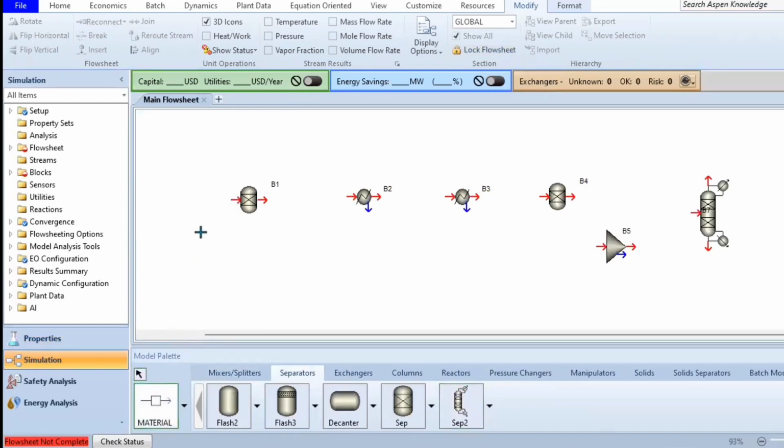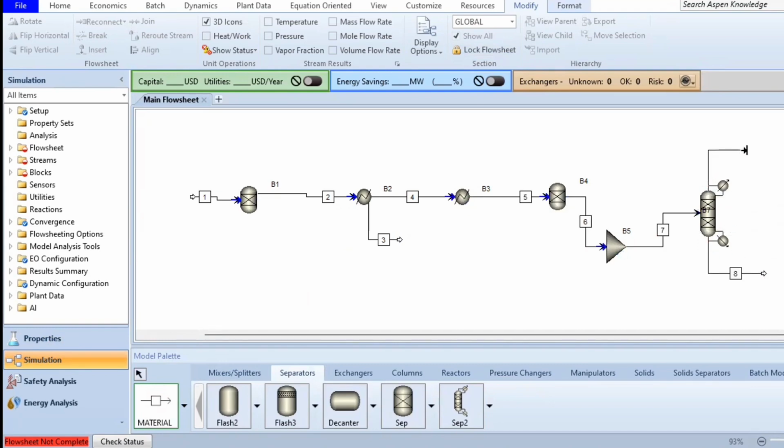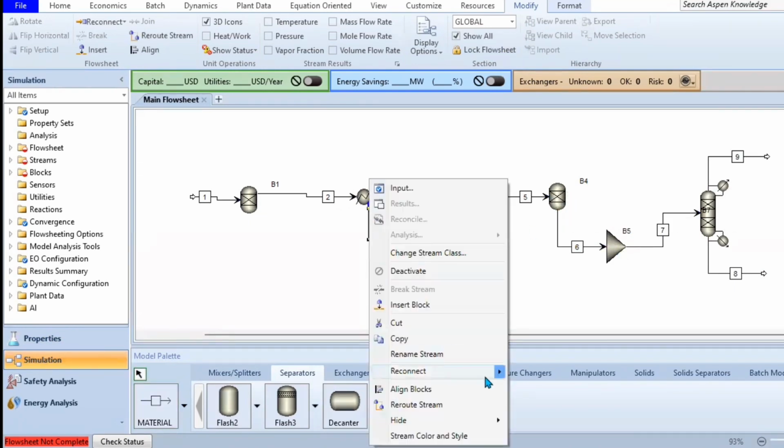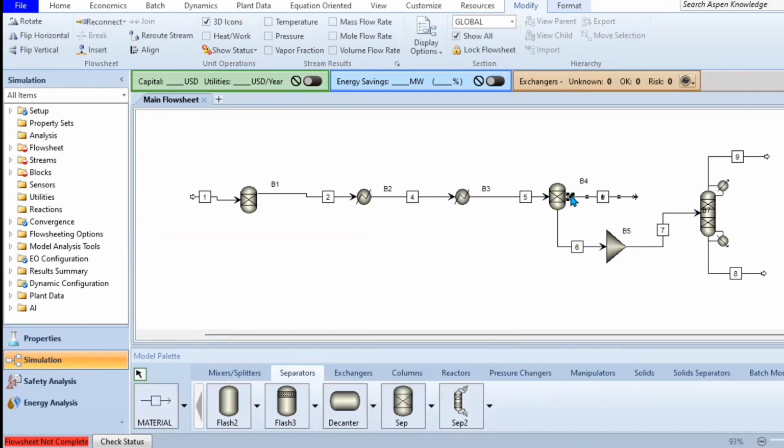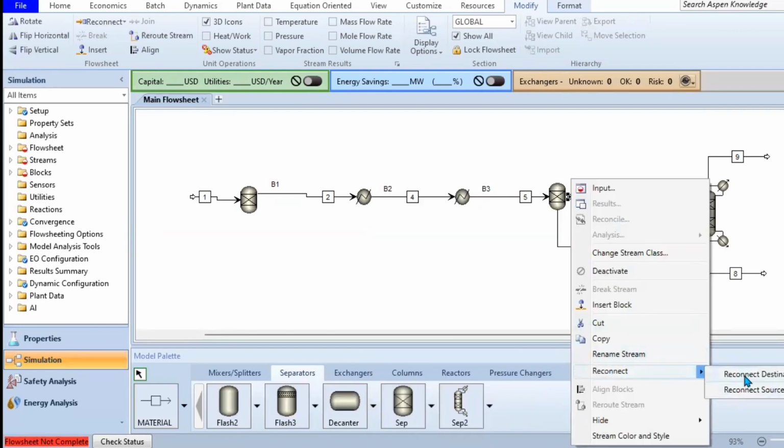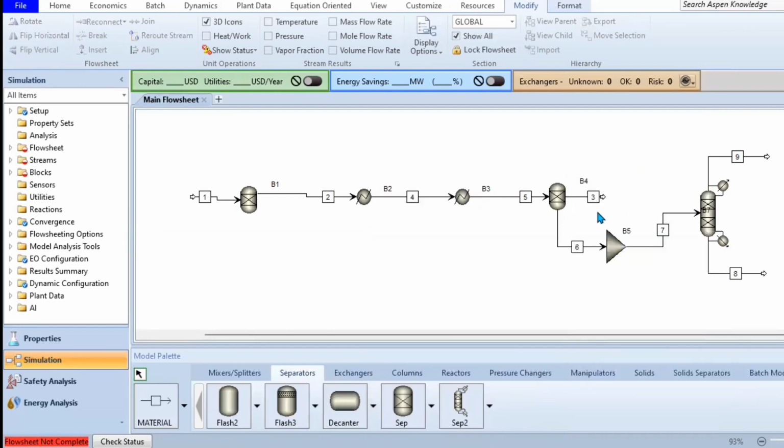We can also specify the streams that are going into and out of our equipment. So we are going to have a feed stream. We'll have 2 streams exiting from the separator, the top stream being the vapor and the bottom stream being the liquid. The streams will be connected respectively. Also, labeling the streams makes it easier as a point of reference, as well as labeling our equipment accordingly. There is no strict rule on how you should label. You can label per preference.